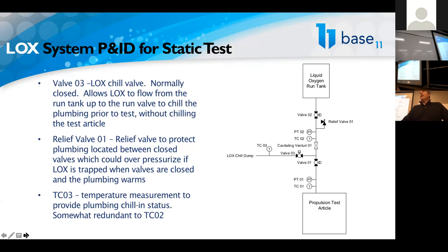These are not an ASME code. This is part of your fluid system, so this is more the B31.3 type of code requirement. We don't want to set the relief valve any higher than the components, but generally speaking, we can go right at the pressure.